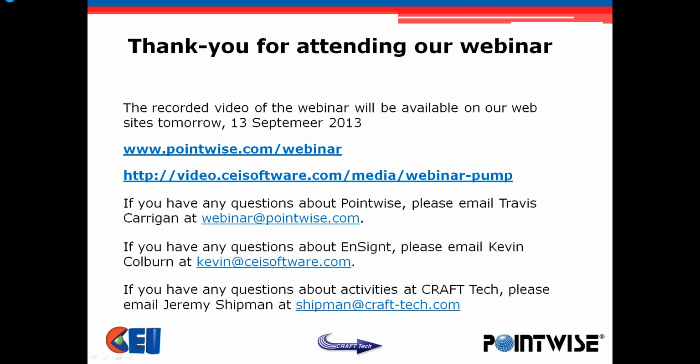Another question was any specific relation to grid size, and I'm thinking maybe this is along the lines of, was a grid study conducted for this analysis? There was not a rigorous grid study that was done. However, typically we'll start a case and look at whether we are resolving the features that we need to resolve, and then there's some extra work done on the grid to do that. But for a case this size, there was not a rigorous grid resolution study.